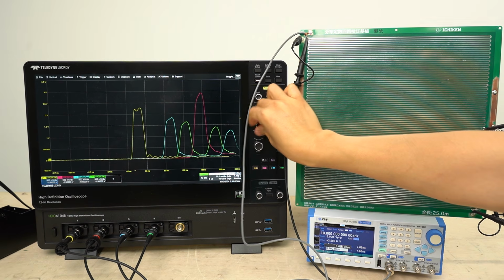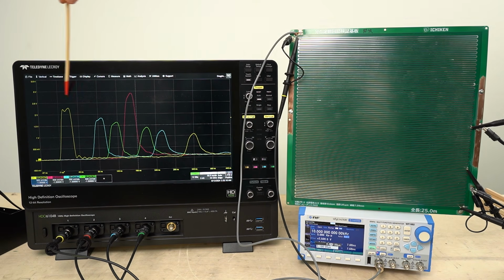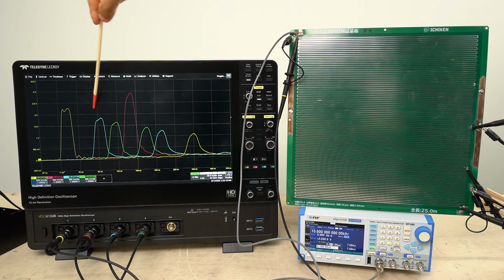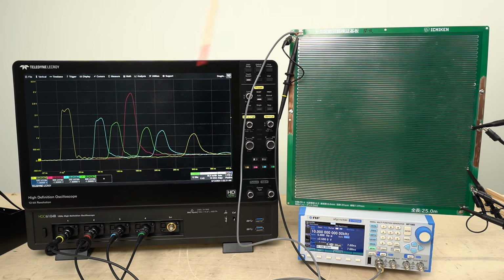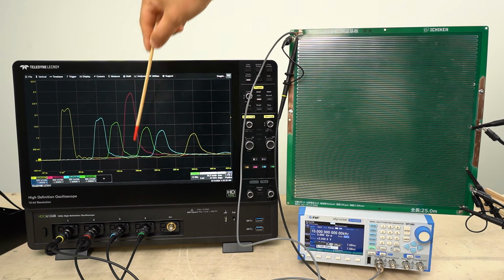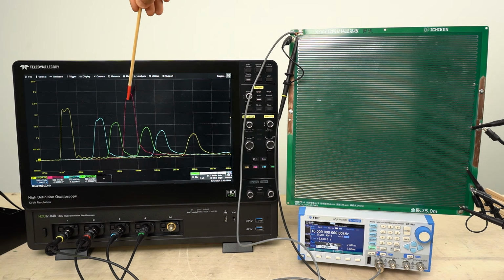Let's shift the time base a little. First, we apply a voltage at this point. You can see the pulse waveform here. As the signal propagates along the long copper trace, it reaches this 50% point. The amplitude drops as it travels, but the shape stays the same. Then it reaches the 75% point along the trace. After that, it continues to propagate and finally arrives here. This red waveform shows the voltage at the open end of the trace. At the open end, the signal is reflected, and the amplitude becomes roughly twice as large.